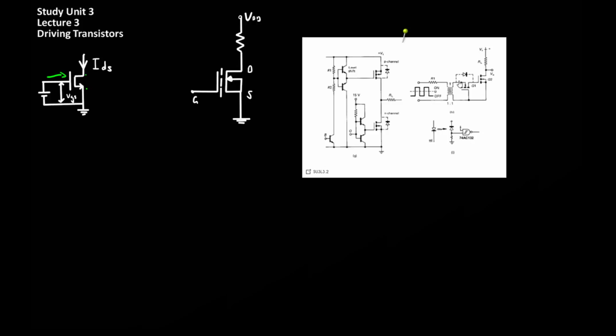When the device turns on, the parasitic diode present in Q1 allows a forward conduction path to charge the device, and will keep it so until a negative pulse turns on Q1, allowing this device to discharge and thus turning off Q2. Finally, example I is another example of using optical isolation to control the TTL gate, which drives the input of the power MOSFET.